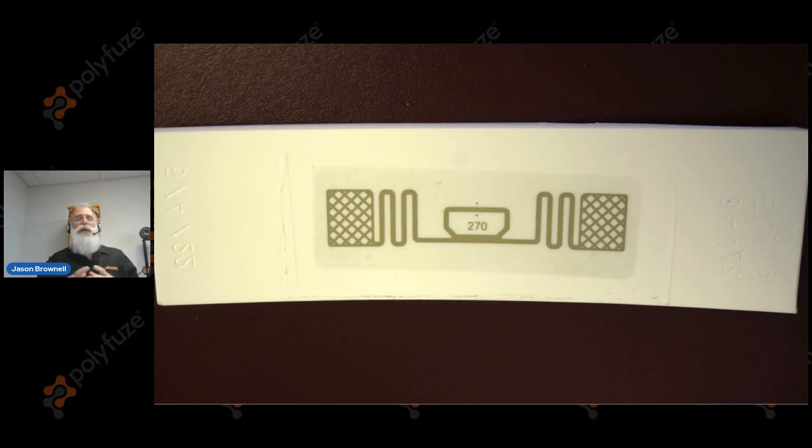What I mean by fusible is that everything we do here at Molding Graphics and Polyfuse is creating a label that is plastic, and through different methods of heat, we fuse it together with the base plastic itself. What you're looking at here is not adhered, it's actually melted into the surface of that plastic. I want to make sure everybody understands that we're not adhering, we're actually fusing together, which is where the whole polymer fusion idea comes from.